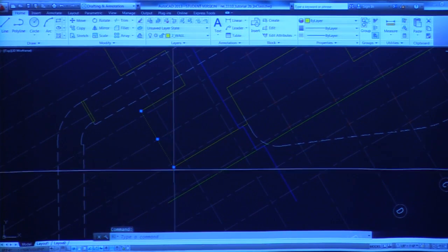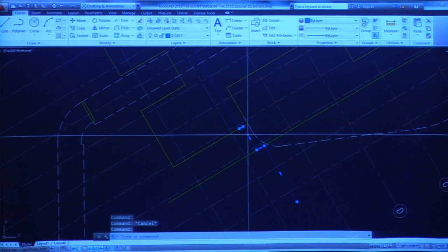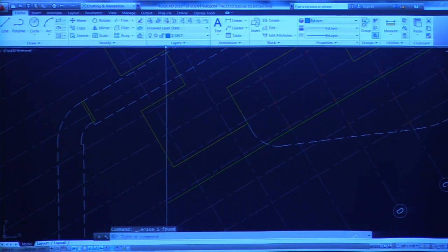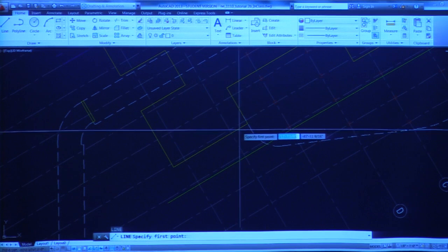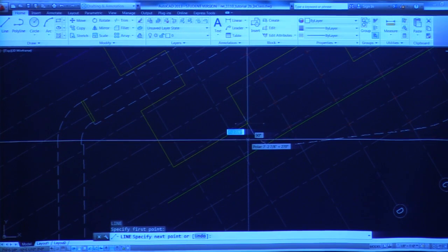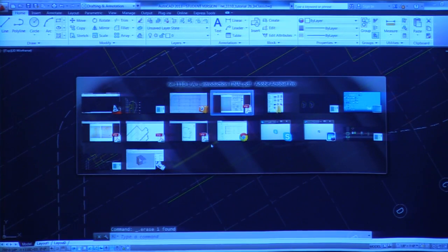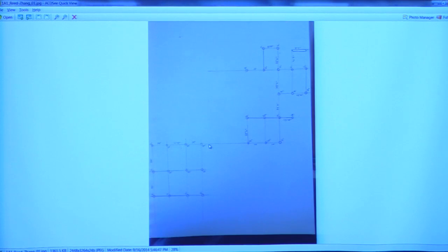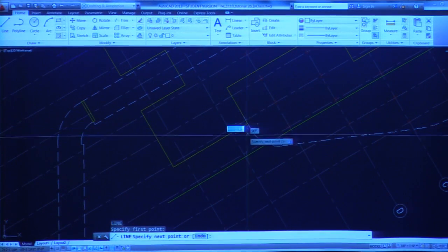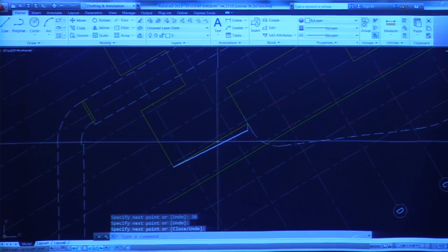And the 0 point I'm going to pick is right at that corner where the ground drops away to the plaza below. I'm actually not going to use that line right now. And so then I can start to construct, using just layer 0 right now, vertical lines that will give me the right height. I might have dimensions on that. I might not, actually. No. So let's say that the difference that it drops there, I think we looked at this in class today, is probably about 3 feet. So if I drop 3 feet and I go back here, that's starting to give me that slope.